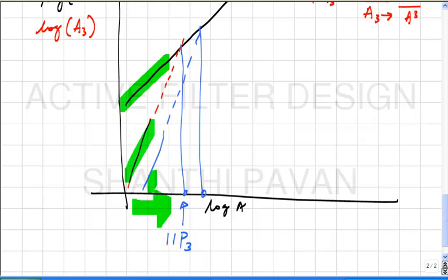Even if you have a 10 megahertz bandwidth centered at 2 gigahertz, I will choose, for example, 1.999 gigahertz and 2.001 gigahertz. So these are two tones which are spaced 2 megahertz apart. So the intermodulation tones will also lie within the signal band, correct? And they are not attenuated.